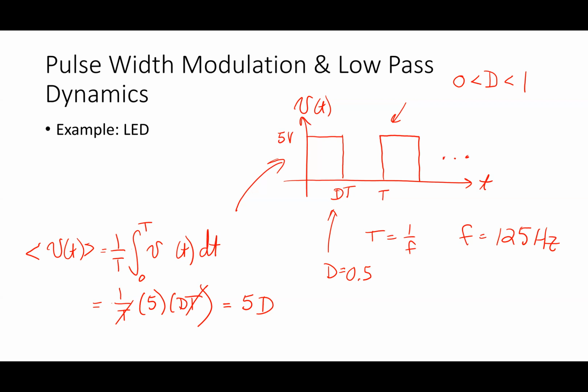Now you should have seen it got a little bit less bright. Now, if I do the opposite of that, I think the highest I can take this guy is 80%. Enter. So that is brighter than it was before, right? So if you talk, people talk about LED drivers, right? That's what an LED driver does, is it basically just creates a square wave that goes into this LED to change its brightness up and down, right? It just is a dimmer switch control.